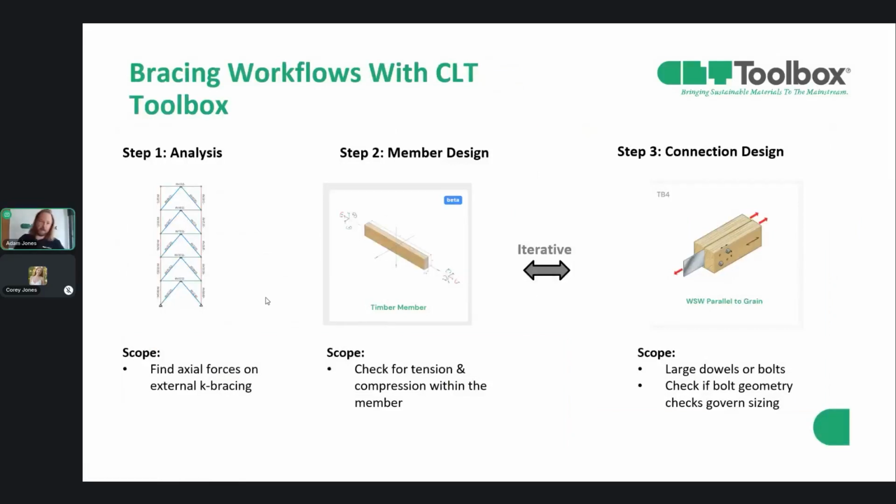Next, we're going to look at another advanced calculation workflow, which can work outside with other software examples out there, your Microstran, Spacegass, Lusas, whatever it might be. So we're going to be doing a lateral K-brace design. So step 1 is the analysis. Currently, this is done outside of CLT Toolbox.